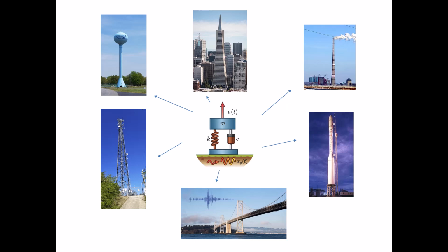And what we'd like to do as a first approximation is model each of these large structures as a single degree of freedom spring mass system and then subject it to a base excitation. We're going to go through some sample calculations for that today using the El Centro earthquake acceleration time history. Now these are large structures, but we can have smaller equipment, like maybe a heating, ventilation, and air conditioning unit, that we would also apply this same type of model to as well.